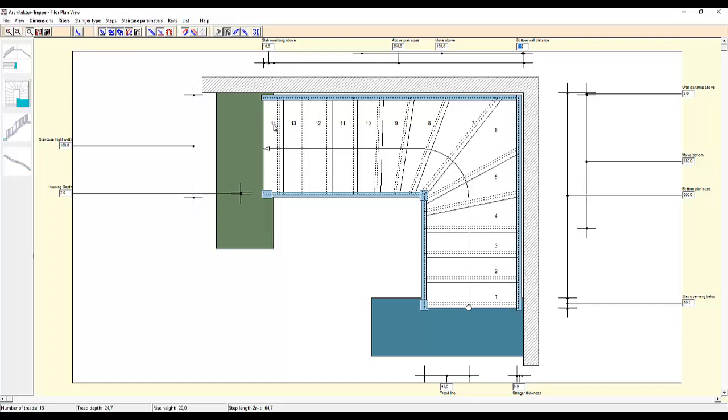This is because the last one is at the same height as the slab where we are landing, and for this reason it is not really considered, because sometimes you don't need the last step, so you delete it. So the real calculation considers one step less. But of course the landing is the slab, because we wrote before to arrive at 2 meters and 80 centimeters. But there is other information, the tread depth.